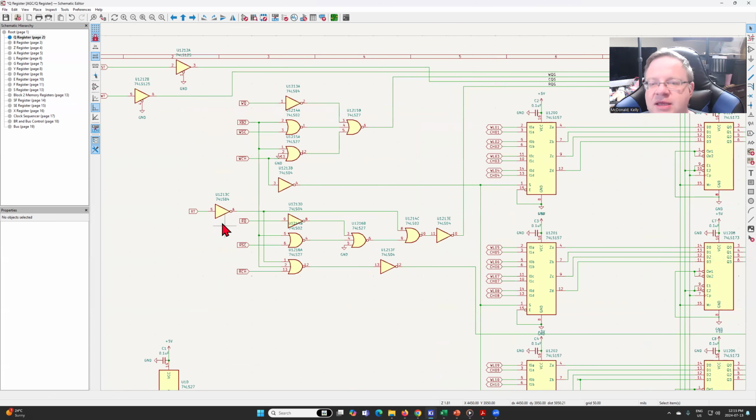The right side is fairly similar, but because we have 2 buses that we're writing out onto, we split the control signals out 2 ways. We have this top layer here, which is with our write timer. When we have the write timer pulse, that's going to be incorporated into our logic to determine when we push data out onto the bus.